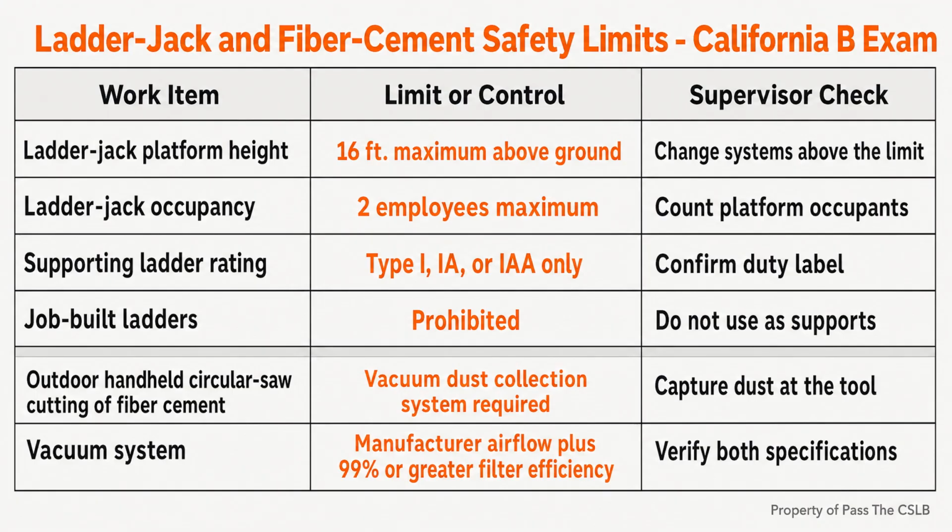At the base, I identify the material before I reach for a number. Wood above earth is 6 inches. Wood above paved surfaces is 2 inches. A stucco weep screed above earth is 4 inches. The screed above paving is 2 inches. I measure the finish condition and account for later soil, mulch, paving, and trim work.